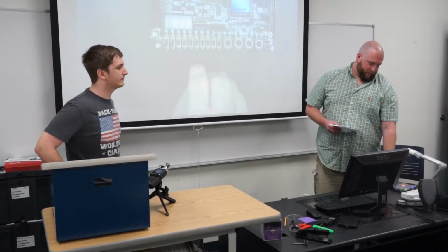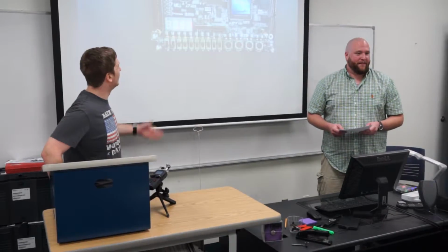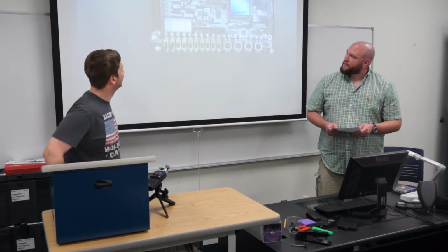So what is your clock running at? 32 hertz, after you divided it down. Well, it started off at 50 megahertz, and it divided to 1 megahertz, and then divided that by 32, 3 times down to 32 hertz. So its current speed is 32 hertz, that way it displays slow enough that you can read it cycling through the numbers. But it still doesn't match the frame rate of the camera. Somewhat, you can tell a little bit.